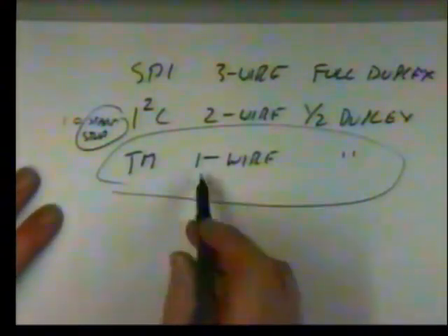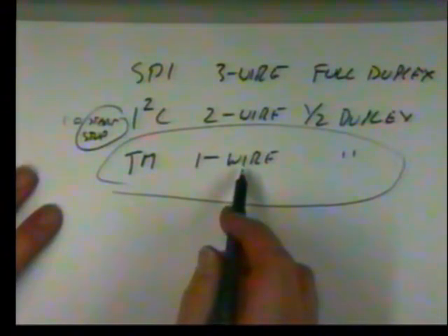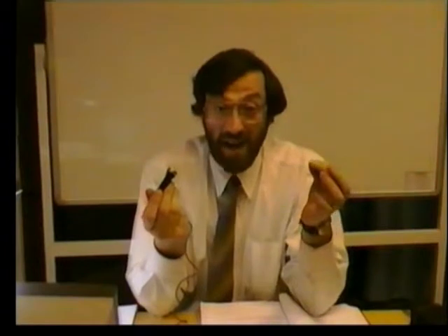And the most compact standard of all, the touch memory standard, one wire standard, combined the clock and the data together. Now, they were originally developed actually purely for these touch memories, so it's often called the touch memory standard. And the idea was that you could have these touch memory probes built into the board. You came along with the memory, you literally touch on. You might have seen these actually. I've seen these on a lot of vending machines these days. I've seen them in little casinos where you buy your chips on these little buttons, and you use that to play the fruit machines. But you touch that on, it sucks the data in and out, and then you take that data off to another station and you touch it on.